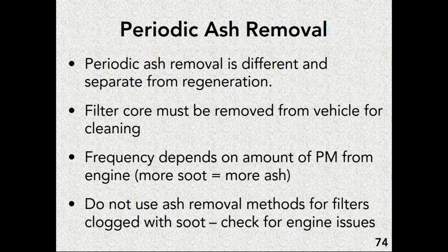So one of the things that I talk about in a couple different classes I have are trucks that are used a fair amount on dirt roads or on construction sites, because the dust that is produced on those areas will oftentimes make its way past the air intake system and into the combustion process. Dust can be made up of combustible materials, but it's also a fair amount of rock and silicates, and those don't burn at the temperatures that we're regenerating these filtration systems at.